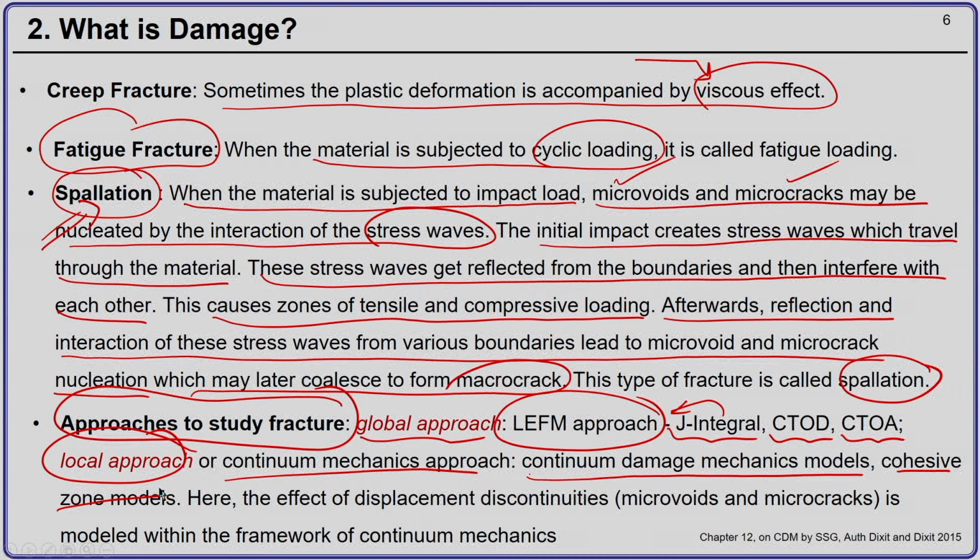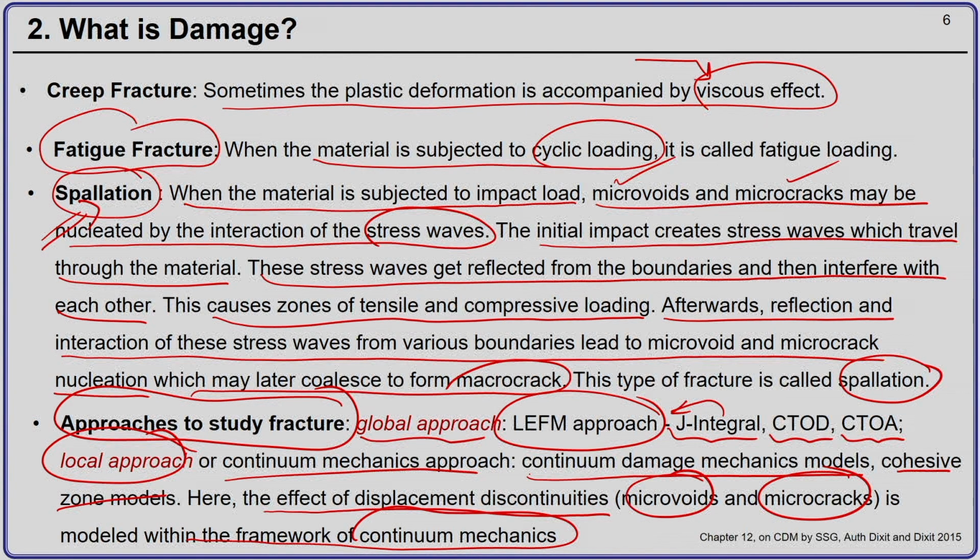In the local approach the effect of displacement discontinuities, that is the micro voids and micro cracks, is modeled within the framework of continuum mechanics. We have already discussed some part of continuum mechanics in this course, though we did not discuss the thermodynamic part and the constitutive relations part that extensively, but in a pure course on continuum mechanics you would go through those parts which are needed to model continuum damage mechanics or cohesive zone models.